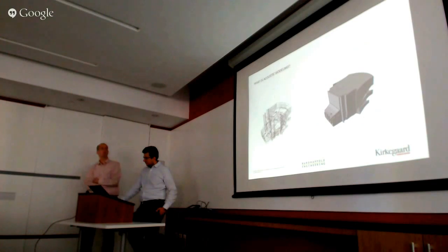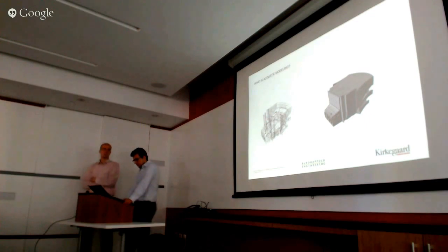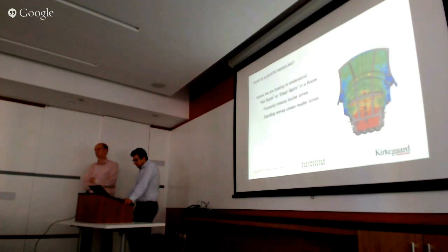The other thing that we need to do when putting together one of these models is determine where the source and where the receiver is. Sometimes that would be, those are various source locations for this specific model. And then we had selected a couple of receivers in the audience area. If we go back a slide real quickly, we can also select areas, audience areas, to compare different zones with one another. So that would be the process of how we like to put together models for acoustic purposes.